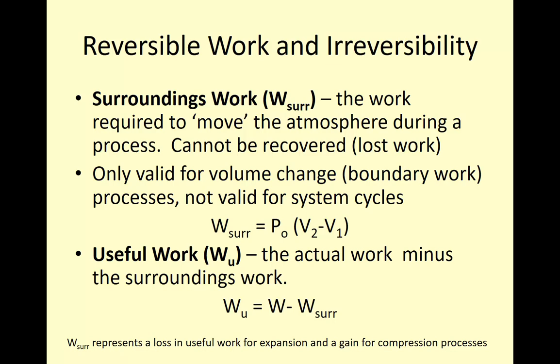Useful work is the actual work done minus the surroundings work. And again, as I mentioned before, the surroundings work is going to be a positive quantity for an expansion process, and it's going to be a negative quantity for a compression process. So it's actually going to serve to increase our quantity of useful work. If our volume 2 is greater than volume 1, then the surroundings work is positive, which means it subtracts from our useful work. And if our volume 2 is less than volume 1, then the surroundings work is negative, which means that it adds to our actual work to give us an even greater term for useful work.